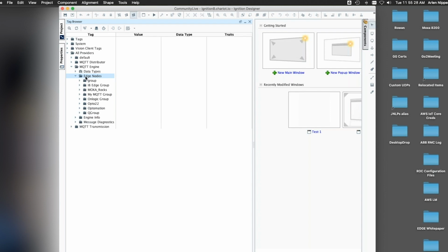redundancy, if you think about one MQTT server, well, because of the Sparkplug specification, the way everything's designed, you can have n number of MQTT servers. Phillips 66 has 6 MQTT servers. Plains Midstream has 4. And with multiple servers and multiple availability groups, we're seeing 5 nines of availability, because if an MQTT server would fail or if a network would fail, everything knows that it's got multiple MQTT servers that can go connect to. And now we've got our Signal Fire sensor in.